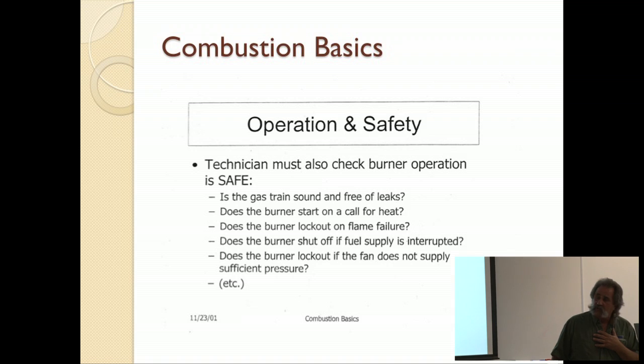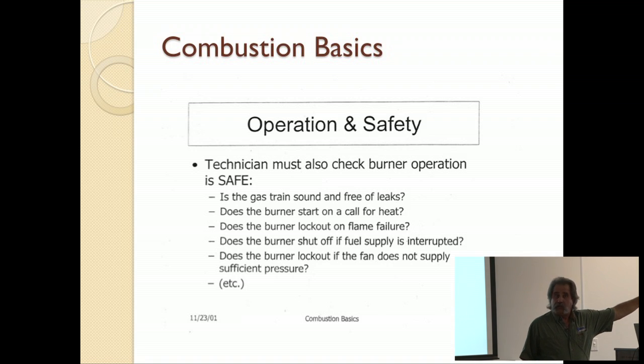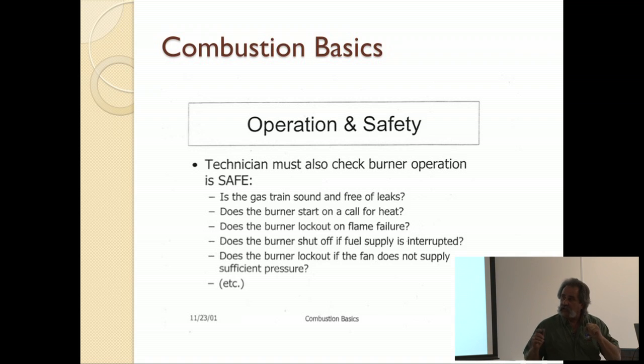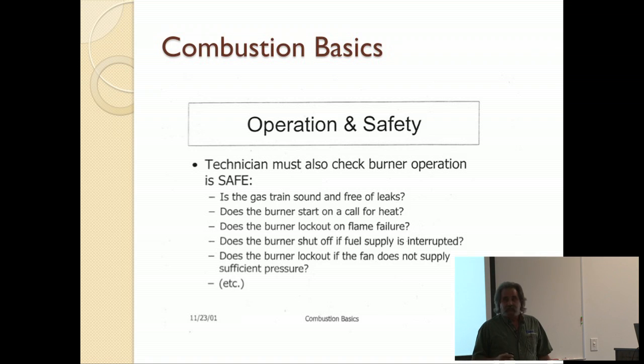Well, unbeknownst to me, because this was a very large installation, outside they have large liquid propane tanks. The last thing you want is liquid propane going into this thing because it's going to expand rapidly and blow like a bomb. So outside they have another boiler house that is supposed to preheat the liquid propane and turn it into a vapor so that when I open my valve, I get vapor. This time I didn't, because I didn't know, and there was no way to know. This was a quarter of a mile away. Nothing told me whether that one was on or off. I made an assumption that it was.